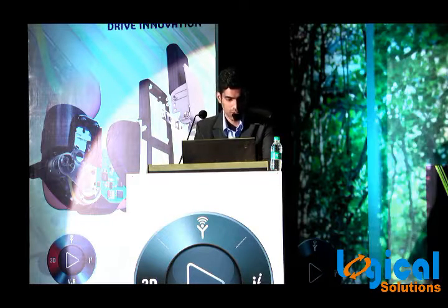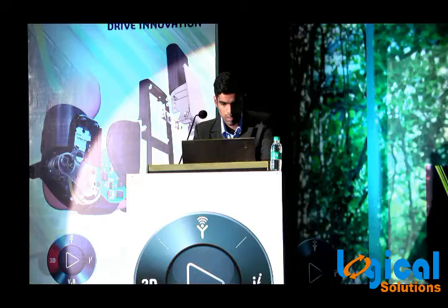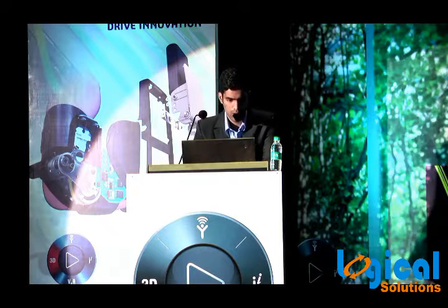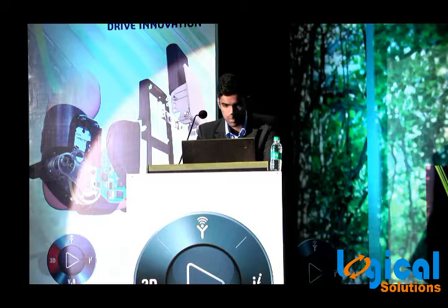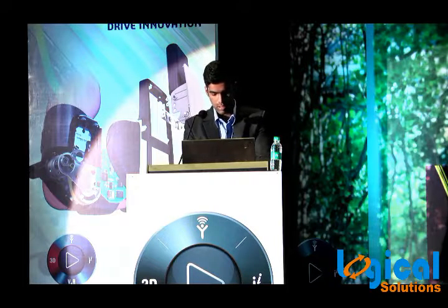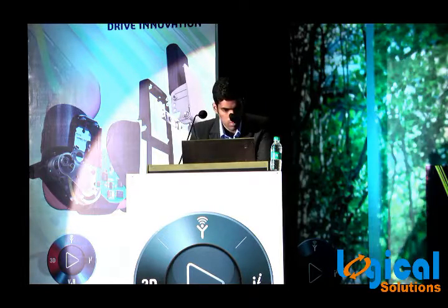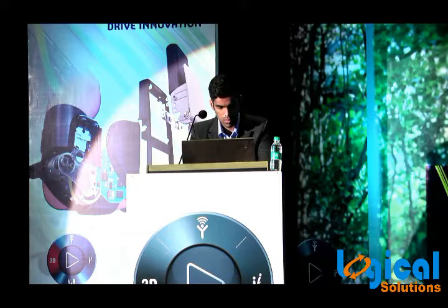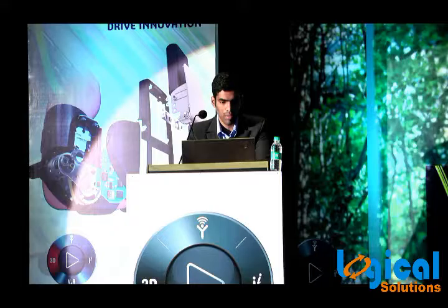Let us make an offset of this, and control the distance. Now this is a fully defined sketch. So I will make a cut of this.